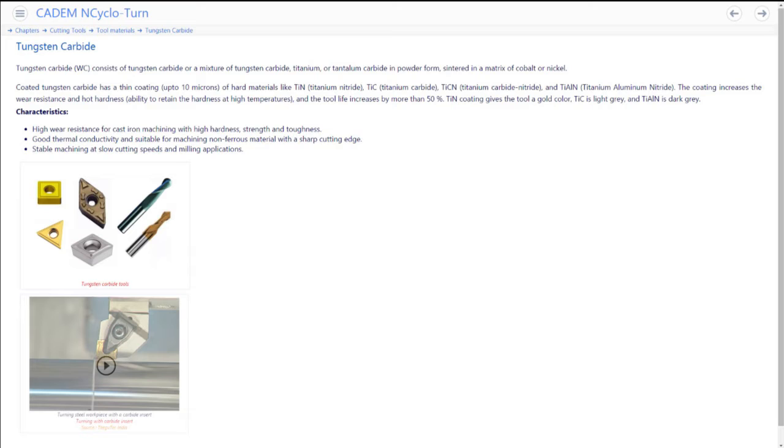Tungsten carbide, commonly called carbide, is the most popular material because it is hard but relatively inexpensive and is used to cut a wide variety of workpiece materials. Inserts are made by combining hard tungsten carbide particles with a soft binder material, which is cobalt. You can achieve different grades of carbide by varying the proportions of the tungsten carbide and binder. Want more hardness? Increase the amount of tungsten carbide and reduce the binder. Want more toughness? Reduce the amount of tungsten carbide and increase the binder.